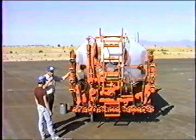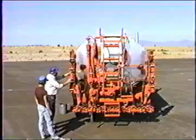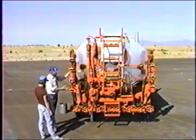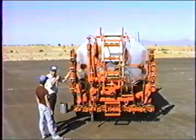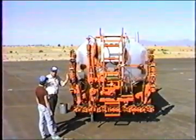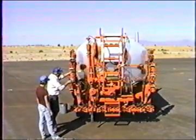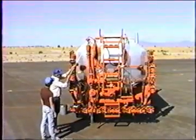Okay, when we turn the master switch on for the spray bar, the bar valves that we've pre-selected are going to open, and if we've pre-selected the full length, when we hit that master switch, 16 feet of spray bar is going to open. Tied to the master switch, remember the relief valve up here.